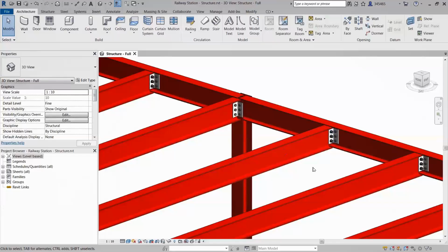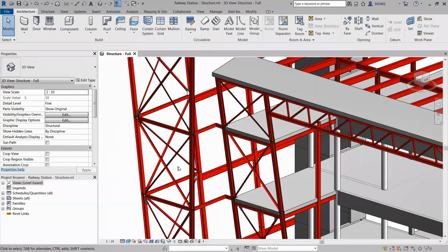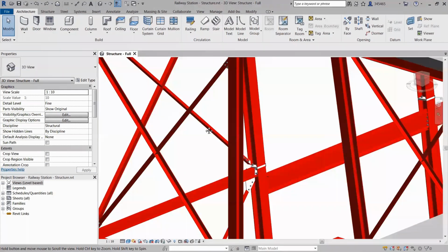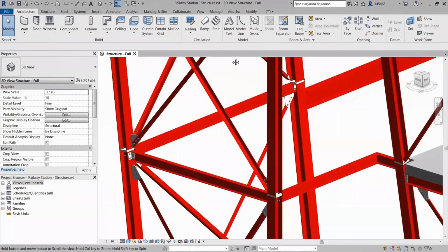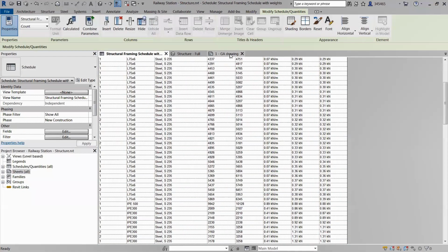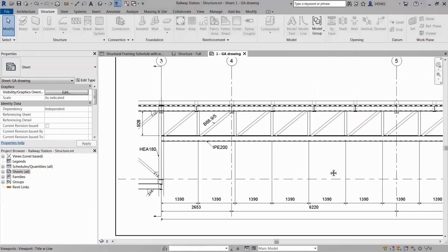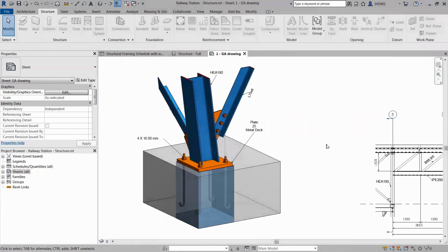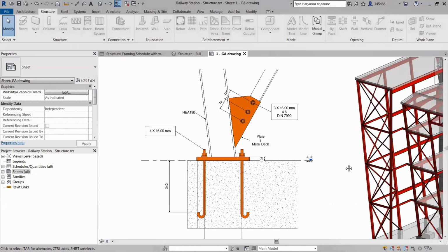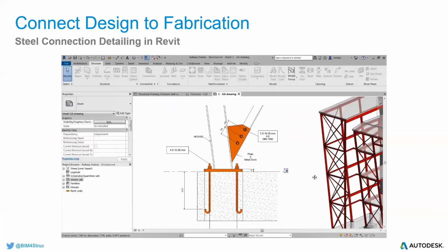So once you have selected it, just to ensure that they meet the required detail level that the structural engineers have specified, then from there, you can automatically start producing the documentation in terms of the details just by cutting the sections and plugging them to the relevant sheets. Like that's the holding down bolt with the corresponding base plates. So it's very, very easy when you work with this kind of workflow to generate your documentation in a multidiscipline